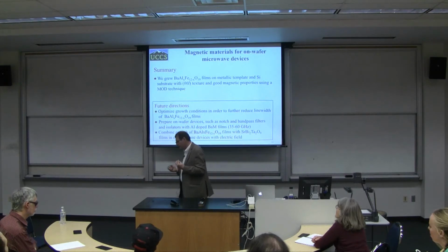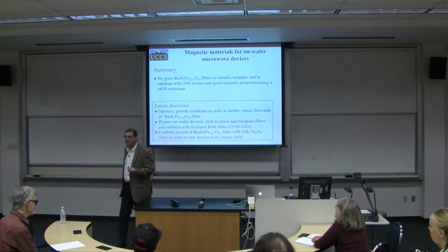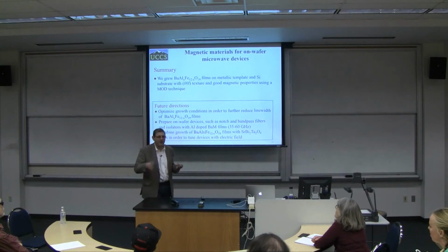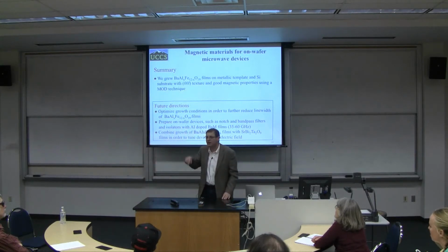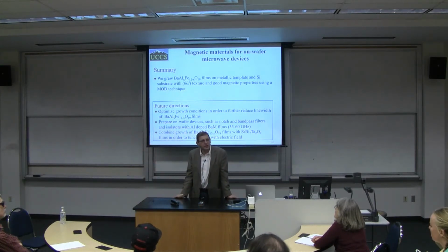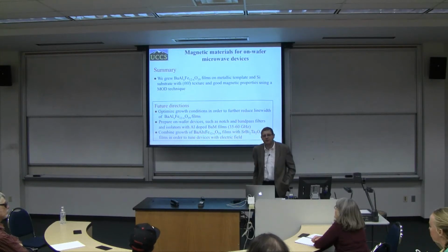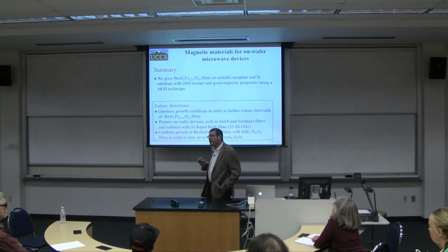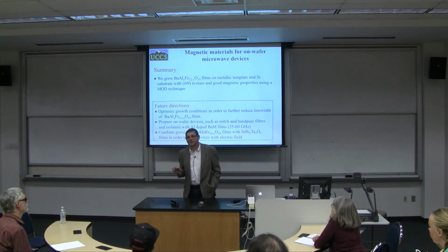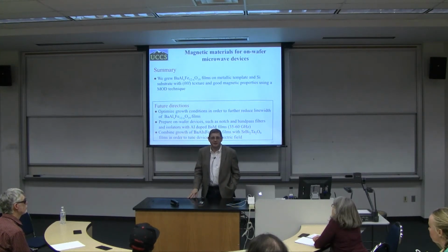The thing is, changing the electric field is very easy. You have function generators which can give you any waveform you want in the nanosecond regime without any problems. Actually, picosecond, let's be honest. We are talking about maybe 50 picoseconds or so. To change a magnetic field, you have to have an electromagnet.